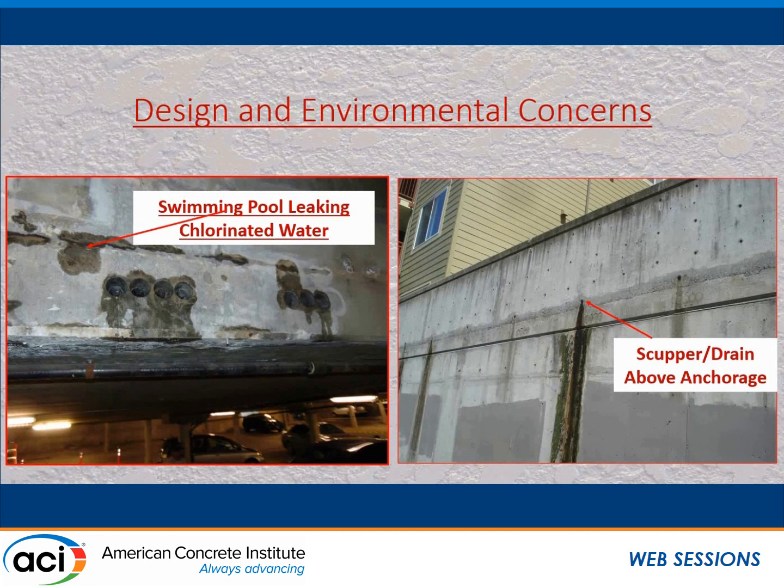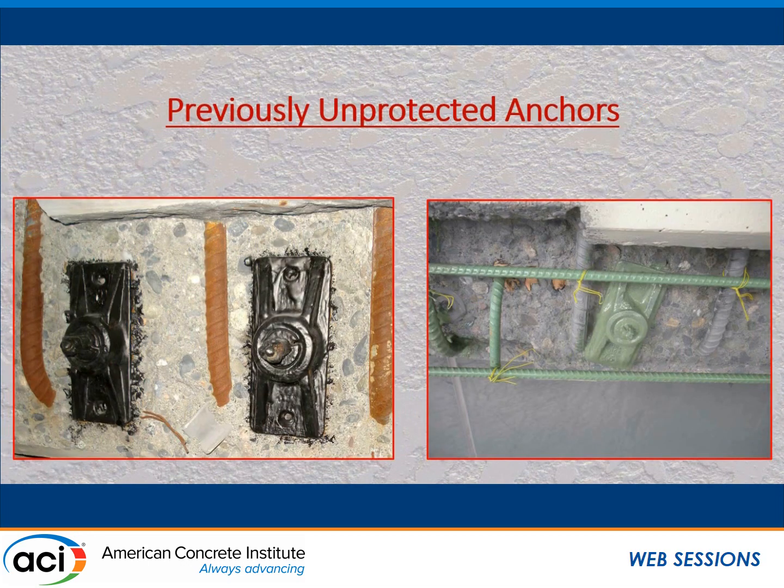On the far right is another detail of where for 20 years, 10 years, 15 years, whatever the number is, water is draining off of a plaza right over the anchorage. And those are details that could be changed or modified to try to eliminate long-term corrosion or problems at your anchorage. So I don't know exactly at what point, I think it was in the late 2000s, that encapsulated systems were either mandated or extremely common, and certainly before 2000 it was not overly common.